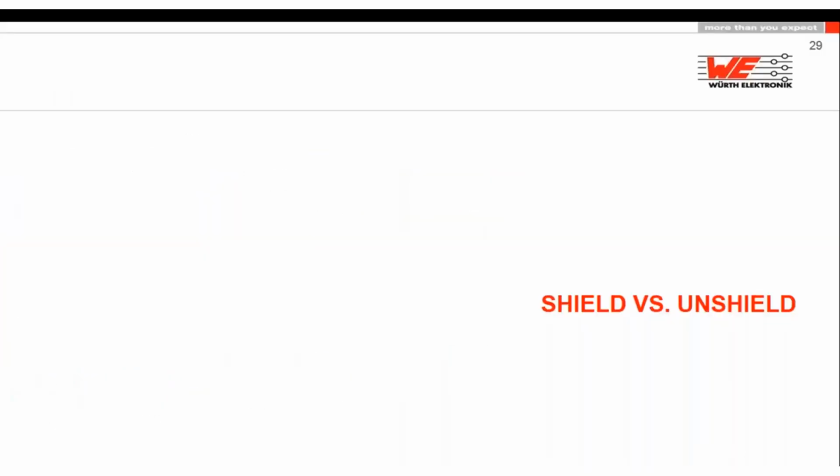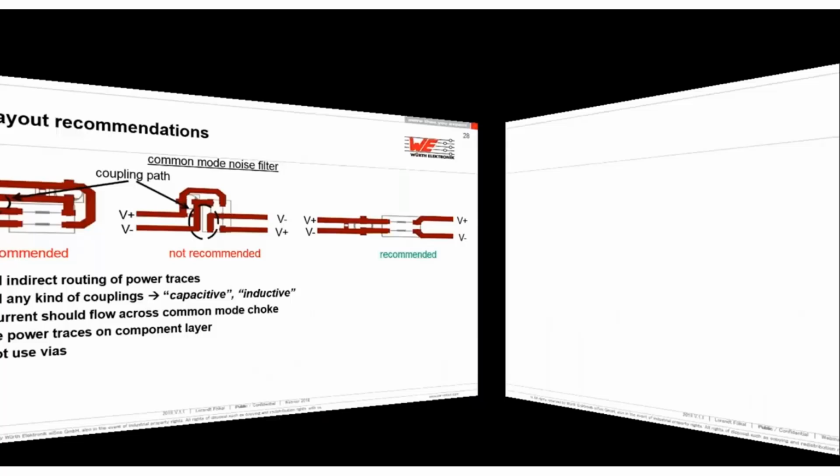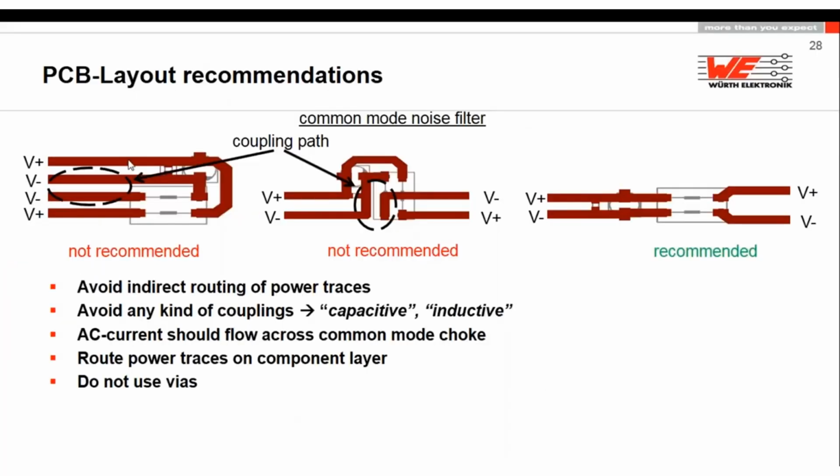Okay, no, it was one click too fast. So this is an experience which was given from a customer. The customer went to the EMC lab. He failed. He asked for support. We helped him somehow. We were with him in the lab, and because he failed, we found the solution. We put an in-air PCB. So we soldered two capacitors directly to the connector, and we soldered an additional common mode choke. And we found out, hey, with this solution, he will pass the EMC test.